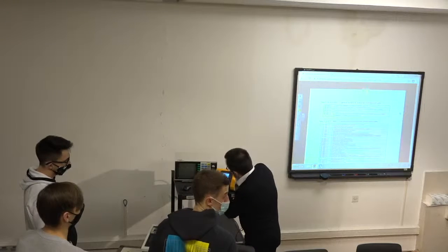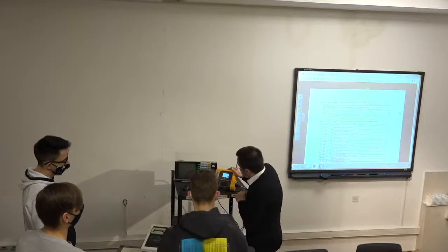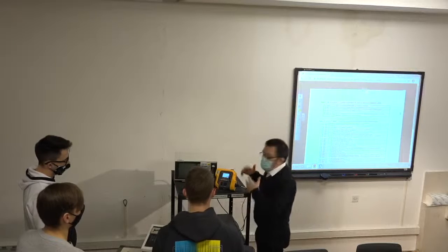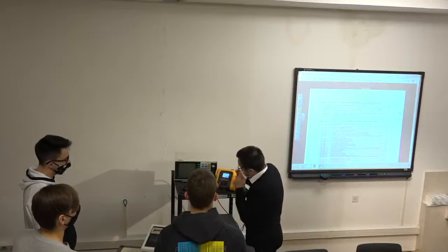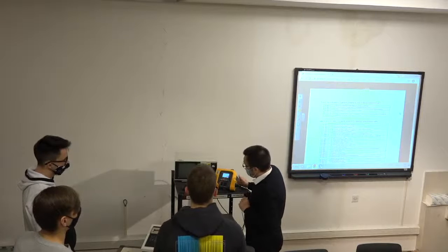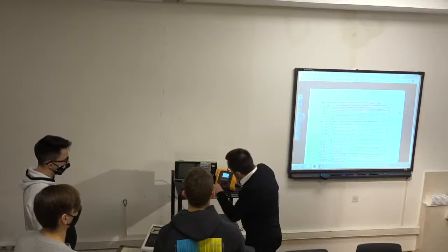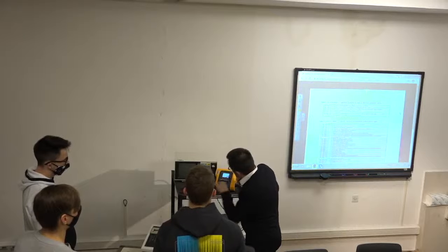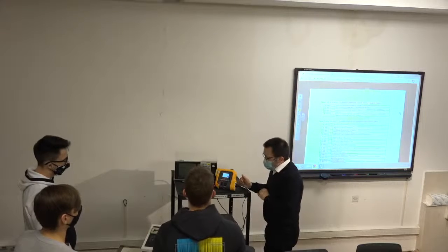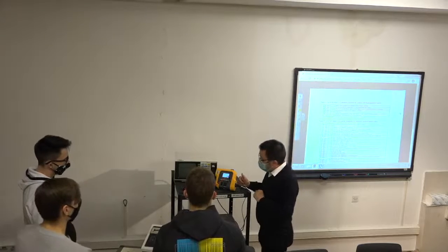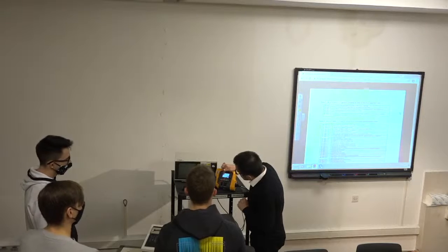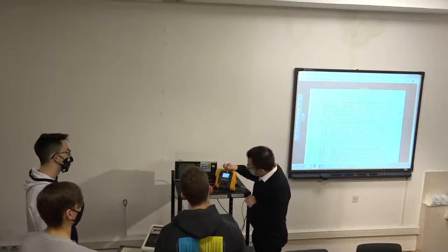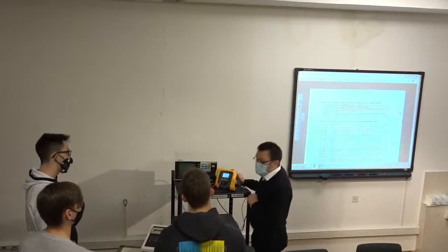Fine. So we made already our selection here, and now it asks what kind of a test you want to do. So there are several tests that you can do. Firstly, let's say this is the voltage. So probably in this case, why it is beeping, okay, is that the voltage between neutral to earth is 0.5 volts.